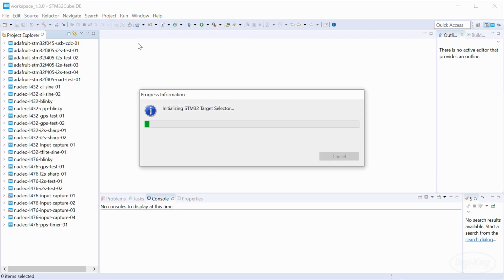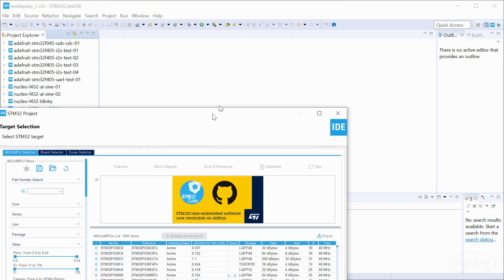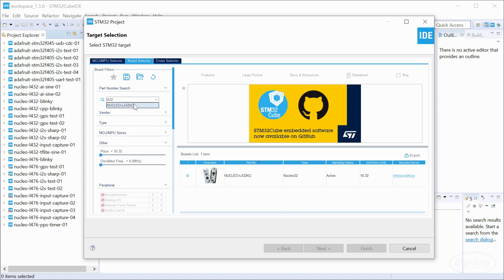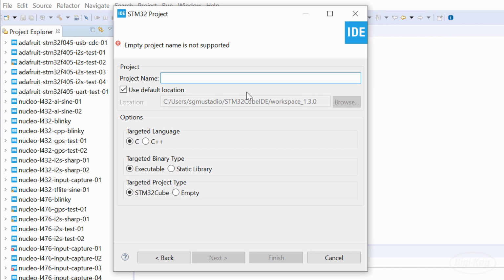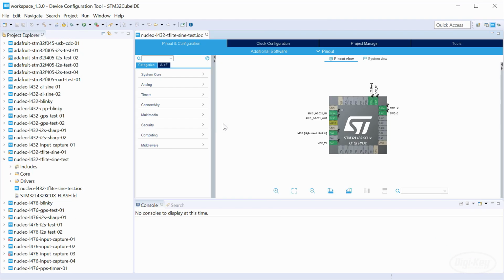I'll be using STM32Cube IDE, but as I mentioned, you can use almost anything. Just note that the steps for including source files and linking object files might be different for your development environment, but the process is essentially the same. I'm going to start a new project for my Nucleo L432KC board. Note that we must use C++ as the target language here, which means choosing to use a C++ compiler, as most of TensorFlow is written in C++.